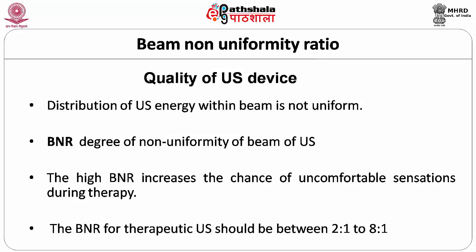The distribution of ultrasound energy within the beam is not uniform. It has high peaks and low peaks of intensity. The degree of non-uniformity of the ultrasound beam is measured as the beam non-uniformity ratio, which is the ratio of the intensity of the highest peak to the average intensity of all peaks. BNR depends on the piezoelectric quality of the crystal of the transducer.